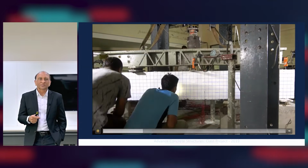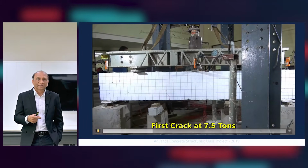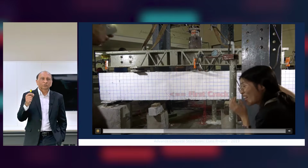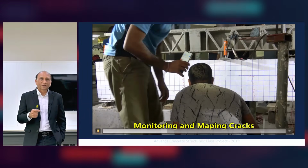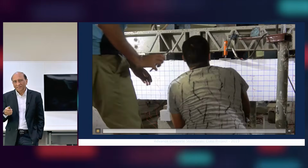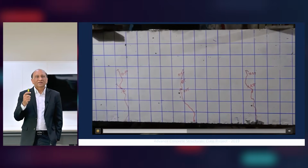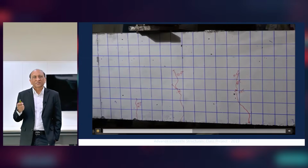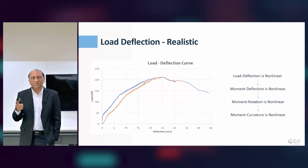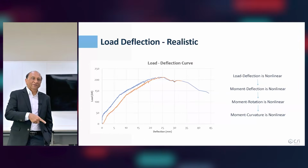You can observe the first crack, for example, note down the load against that first crack, and continue to observe the behavior of the beam until it completely breaks down. So we can get the entire history of deformation of the beam together with the cracks, spacing, location, and thickness, and so on.